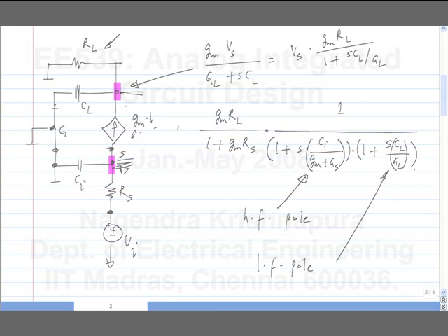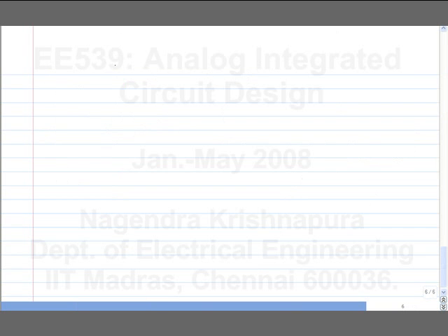No, I mean, if you can identify separate time constants, okay, if I do something like this, then it's not really valid. So there are techniques when you have multiple capacitors and resistors to find out, not exactly, approximately the effect of all of them combined into a single time constant. So there is something known as the method of open circuit time constants. Have you heard of this?